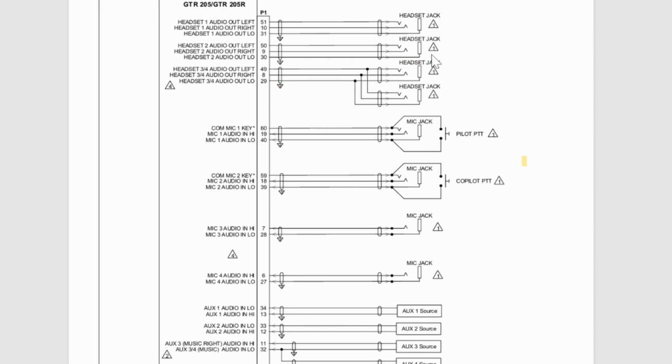But look again, you're using shielded wire to help prevent that buzzing or static or headset noise that you're hearing if you've heard it before on kind of older systems. And again, it's telling us to put that shield and terminate it at the back shell of the Garmin to help prevent that. You can see the other side of the braided wires are just floating. So they're just terminated. They don't go anywhere. They're just sealed up. But the other side gets terminated at the back shell.